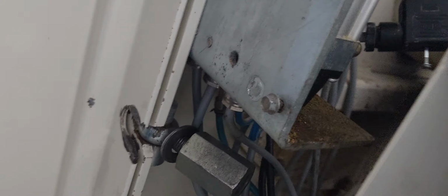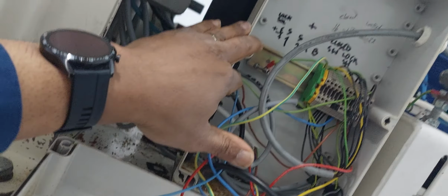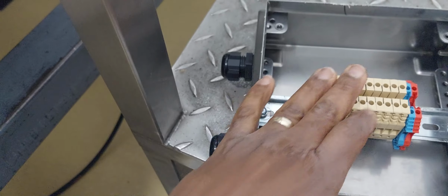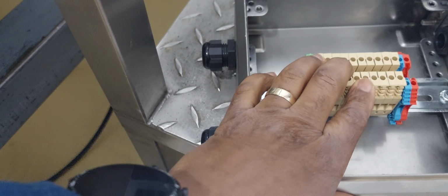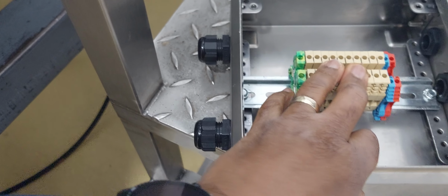Also, there are some limit switches, and there are 2 limit switches here. One of the limit switches is to tell you when the door has been released, and the other one is to tell you when it's open. So all this has to be controlled. So I need to take down this panel now. I've built a little panel which I'm going to use to control the door,